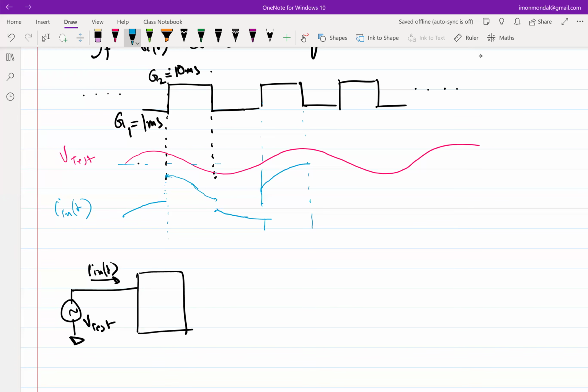Okay, fine. So which essentially means that in these domains, I am getting I_in(t) times 1 millisiemens. Here I am getting I_in(t) times 10 millisiemens, and so on, right? And by the way, when I write it in terms of I_in(t) times 1 millisiemens, I'm assuming that this is limited to within that chunk of time, not any generalized time, okay? So what should this box look like if I need a waveform like that?